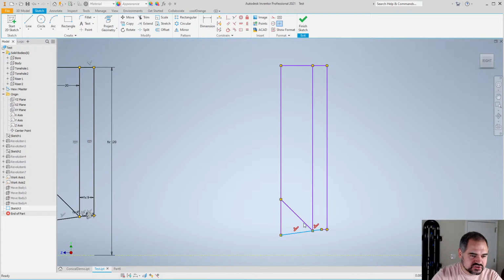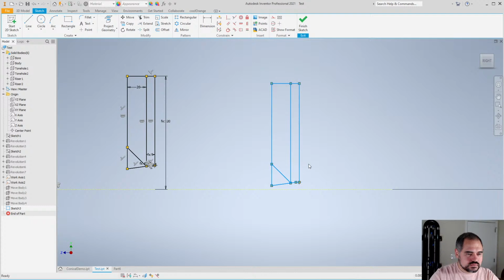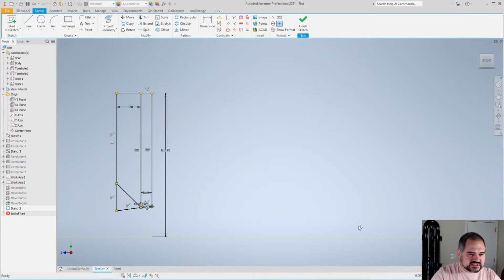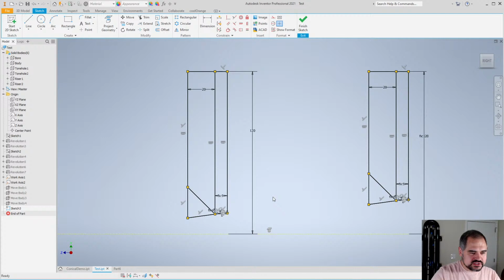So now it's just a whole bunch of dumb lines, and when we try to drag it, Inventor just has to pick something to move, and it usually picks exactly the wrong thing to move. So copy and pasting sketches is a wonderful tool, just make sure everything is fully sketched or fully defined and constrained beforehand. Okay.